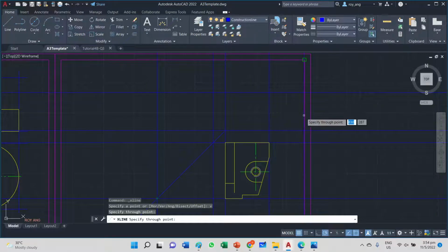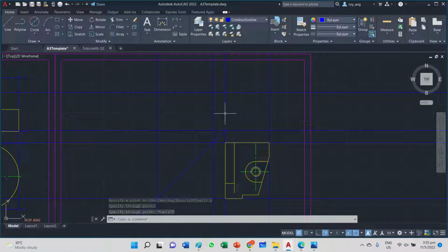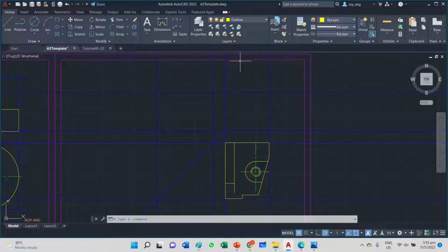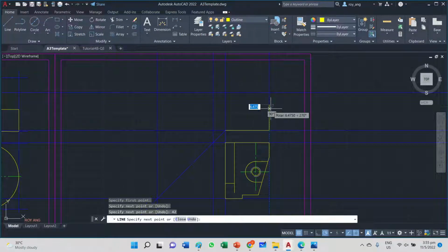So when I'm looking at the drawing, I just drew this line that came down. The next segment is a straight line that runs across, and this is part of the hexagon as well. In the front view, I'm going to draw a straight line, but I do not know where this ends, because this is not given. The dimension of the hexagon's one edge is not given as well. So again, I'll make use of projections to help me complete my drawing. For the height, I make use of my construction line. So I can type here 42, and this is where it starts.